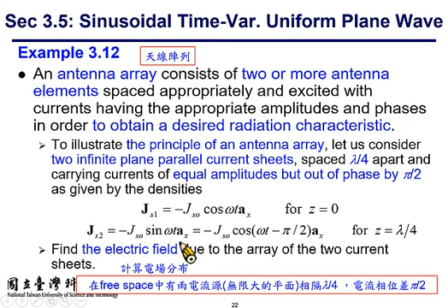The only difference is phase difference. The one is cosine omega t, the other is sine omega t. So we know that they have a 90-degree phase difference. And the sine omega t can be represented alternatively as cosine omega t minus pi over 2. So we know that there is a difference in phase for the two currents as pi over 2.